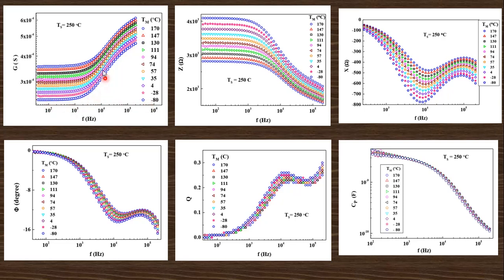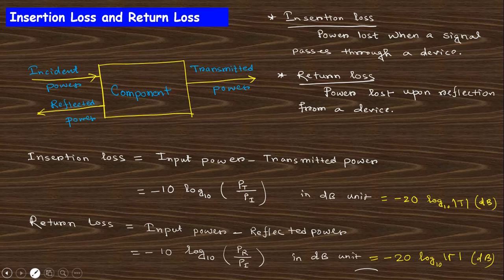We did not get this type of expression, because the frequency range of the instrument that I used was very low, but you can get an idea that there will be a transition in this expression for all these parameters. And all these parameters can be found just by setting the values on this instrument, right? So these are all the things about the impedance analysis meter, from which we can get the AC conductivity of the dielectric material.